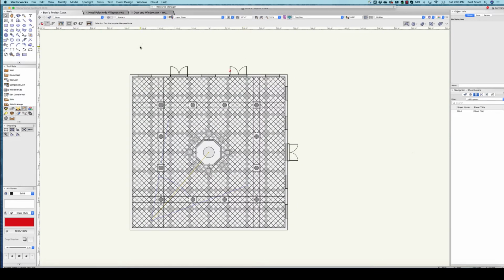My plan here next was to mirror the doors and windows across the center line onto the walls on the other side. But interestingly enough, no matter what I do, when I try to do that, it won't let me do that. And I have looked this up, and I can't seem to find a reason why that won't work. I can, however, mirror the entire wall across the center line. So, and that's easier anyway.